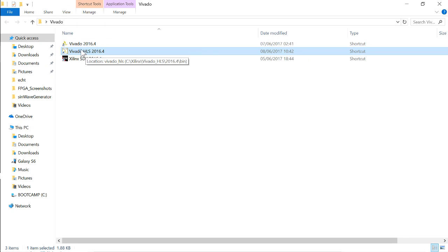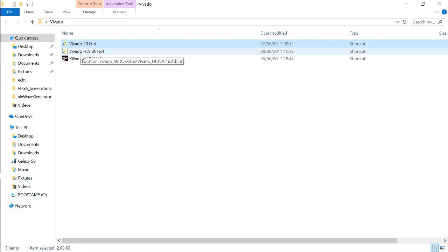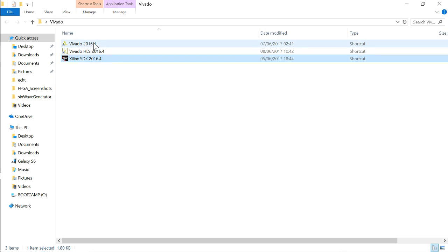So after you have configured the ECHD algorithm, what you can do is press that export RTL button, which essentially sends the configured ECHD algorithm in basically Verilog or VHDL, and export it into this Vivado environment, which can synthesize the FPGA design and have a look at how it actually looks like as part of a whole system. So after you have done that, what you can do is you can export the design that you have synthesized in this environment into the Xilinx SDK environment.